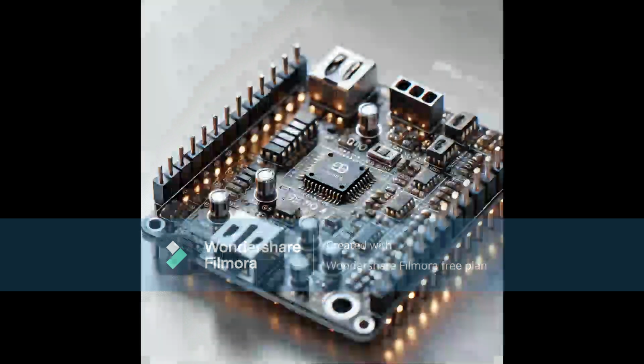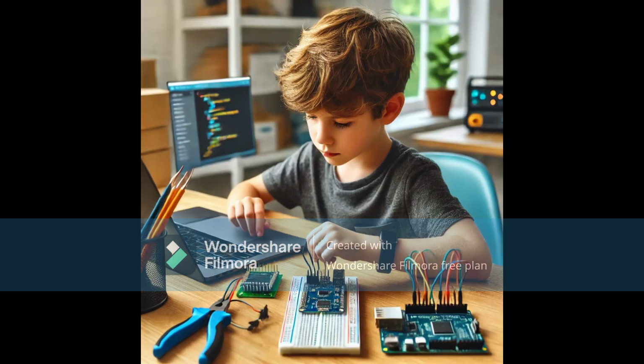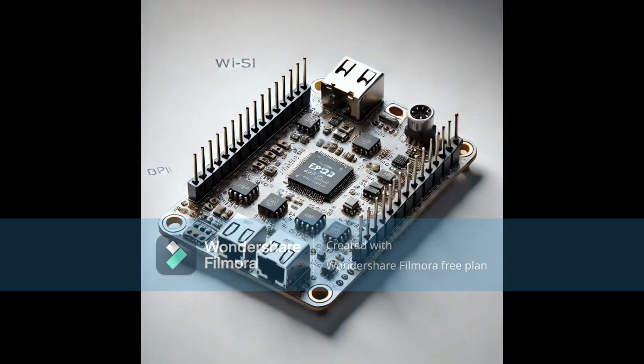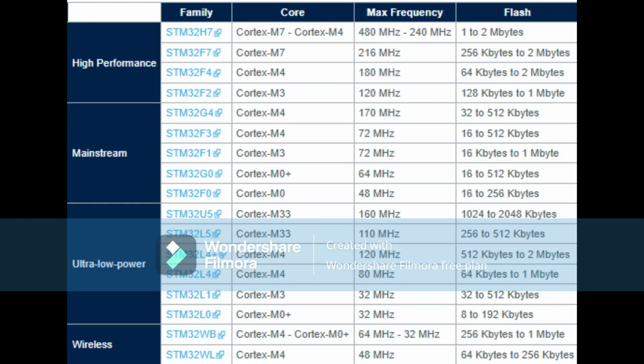Point 3, STM32 resources. A dedicated webpage is available on the ST website for each STM32 family. It contains all relevant documents and resources to guide the end user on how to start developing with the selected STM32 device and exploit it in an efficient way for the user's application. The main relevant documents are: Datasheet, DS, the document describing the electrical characteristics of the product and its pinout. Errata sheet, ES, the document that specifies the known limitations of the product and the ways to work around them if available. Reference manual, RM, the document providing the product specification and describing its registers.